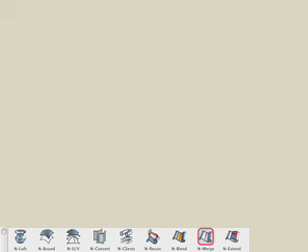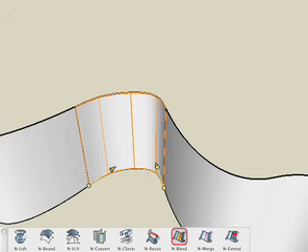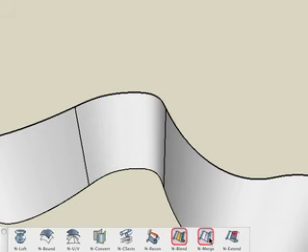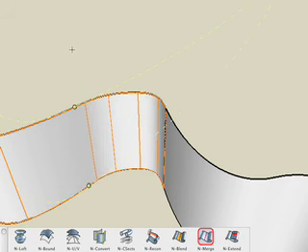Now let's look at the Nurbs Merge tool. We'll begin with 2 extruded splines that were converted to Nurbs, just like we did at the very beginning of this tutorial. Then we'll use the Blend tool to get a separate blended surface between these 2 surfaces. Then, with the Merge tool active, click on the two surfaces and they merge into one continuous Nurbs surface.